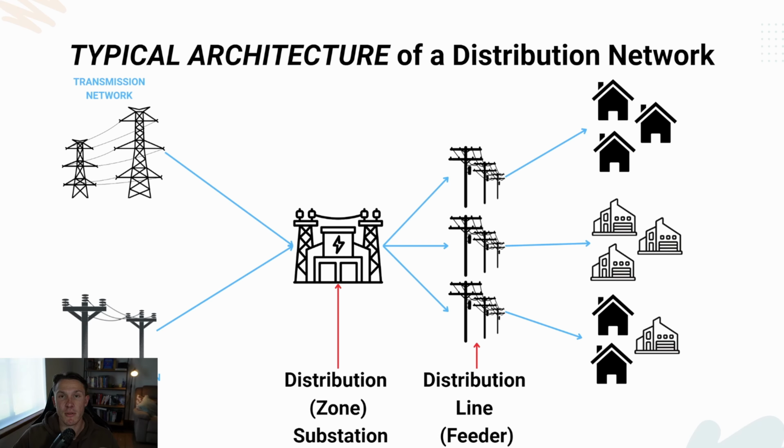So what I refer to as the sub-transmission network is effectively the higher voltage lines that are actually a part of the distribution network. The transmission network connections are actually quite rare in the power system because there are so few transmission lines. What is usually the case is that distribution networks are constructed of a web of, let's say in South Australia, 66 kV lines, which forms its sub-transmission network in the metro.